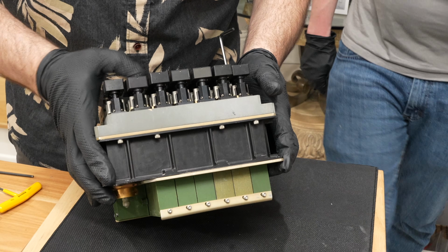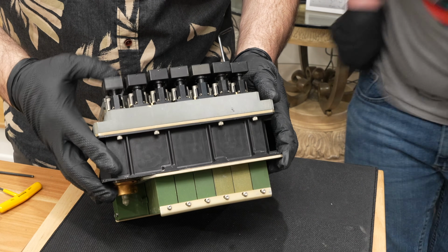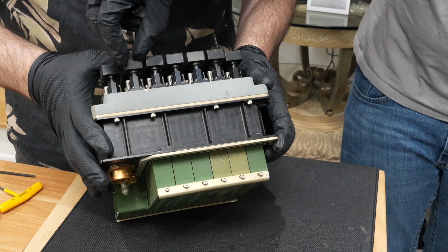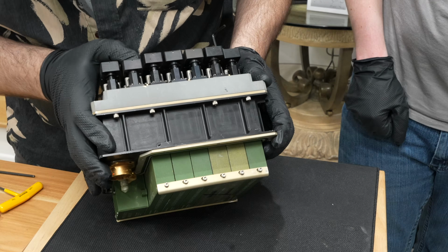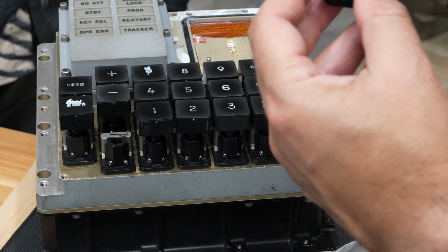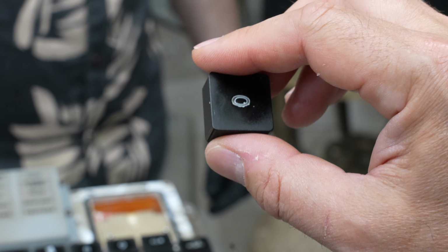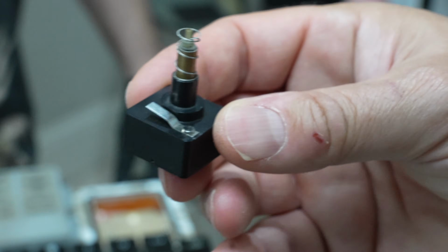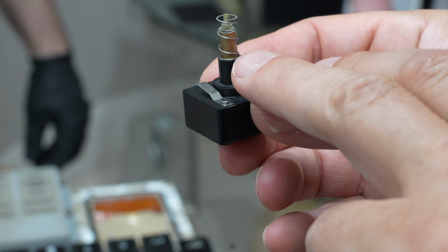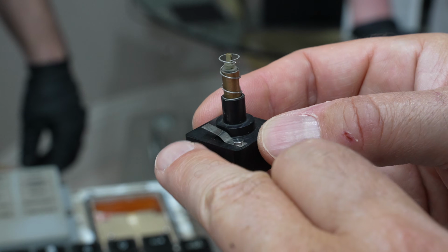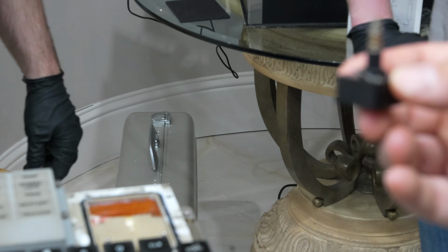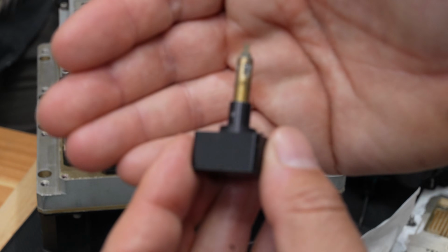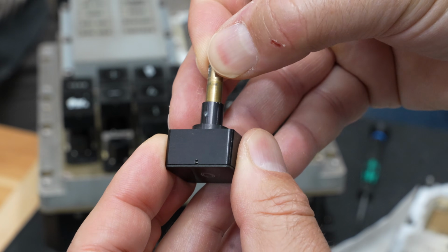This one's definitely sticky. We can fix that. If we undo these set screws, the whole shaft will pull up. I had to do a little bit of surgery on this button. So it's a two-spring design. There's the big spring for a large travel, and then at the end there's a little spring that pushes the switch. So yeah, it goes easy then hard. So the key is stuck, and it's really this part.